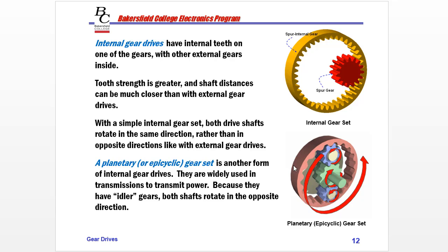It's actually an internal gear. The internal gear, the larger one, will be spinning clockwise as well. So counterclockwise on power, if this is the drive, and then the driven is going to spin in the opposite direction.